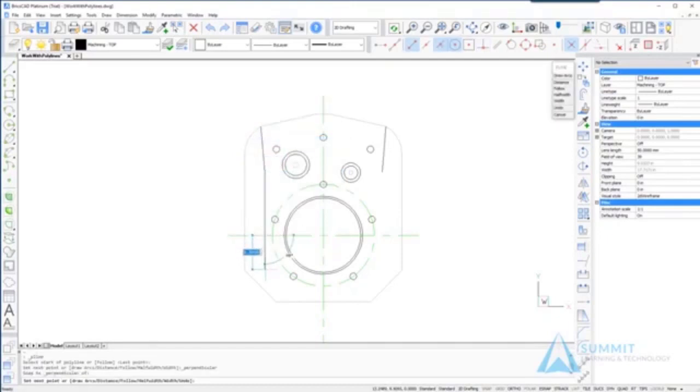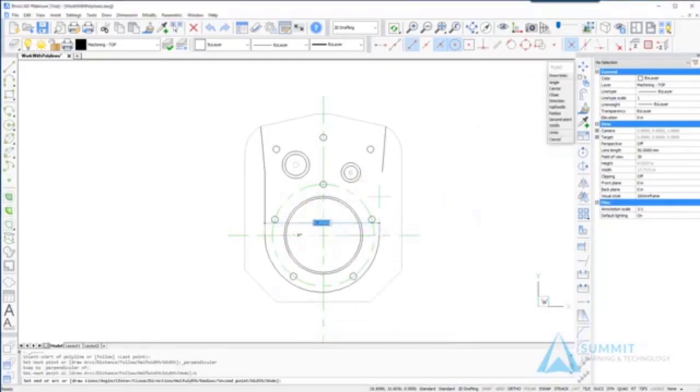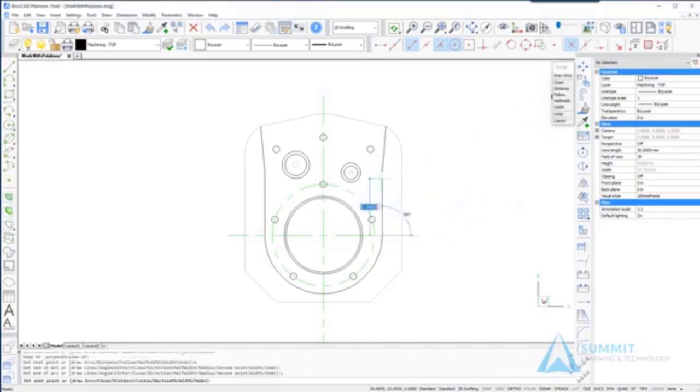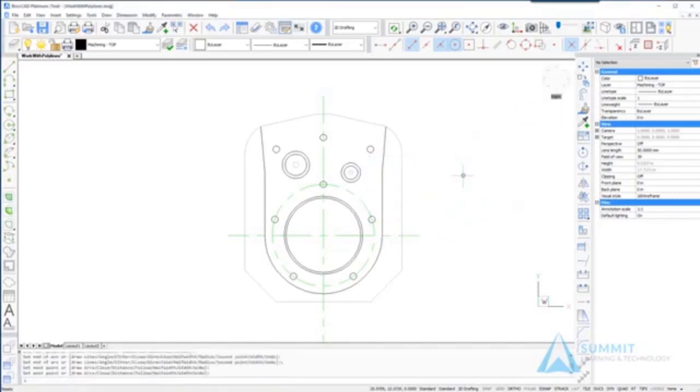Then I want to switch the mode of the polyline command to drawing arcs, and then using snap tracking, find the point on the opposite side of the circle, return back to drawing lines and select that endpoint. So next we'll enter pedit and select the polyline. Starting the pedit command,